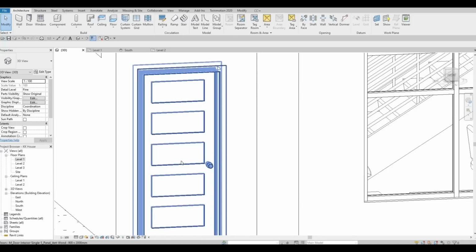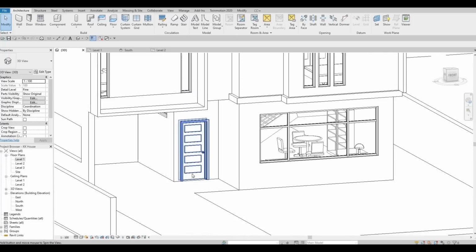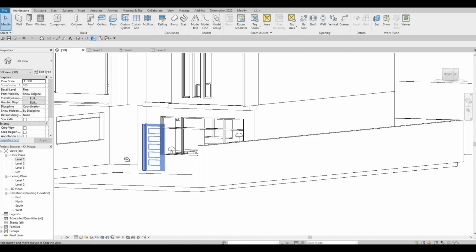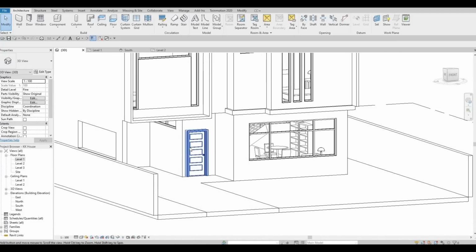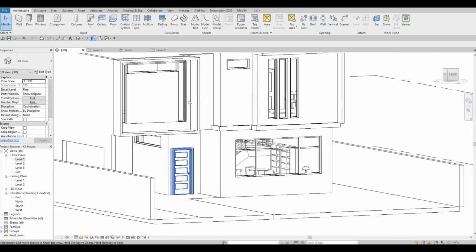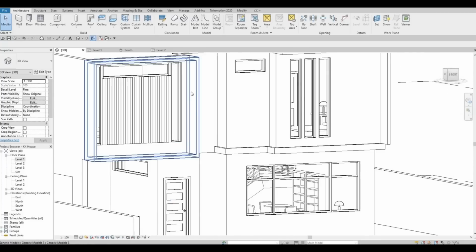As you can see, there's a doorknob, so it looks nicer. The basic one, which is already a default, is without a knob. So I'm gonna change that. And then this one, I want to change the materials on the inside of this. So I could use paint, but if you could see, this is an extrusion.